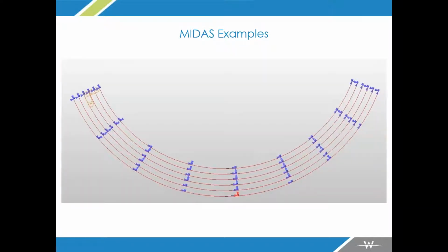As you get into that too, really looking at your boundary conditions is very important. What are your bearings doing? So this was a new bridge, so we were able to control that a lot more. And what we did was we basically took our girder line 3 and we used that as our restraint line. So at this point right here, girder line 3 at the central pier, that's a true fixity for thermal. And then from there, we basically controlled the lateral perpendicular to the center line here of the girder along girder line 3 as the control line. Everything else floated on the bearings.